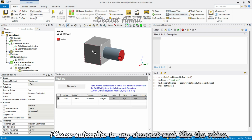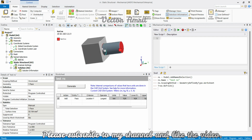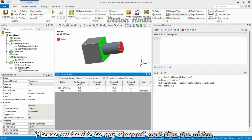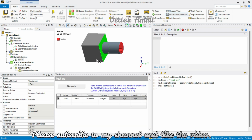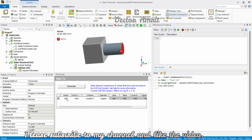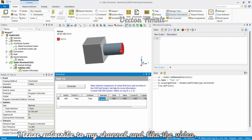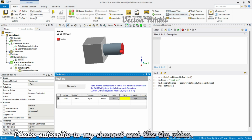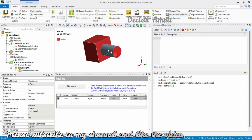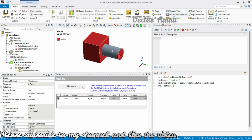Suppose I want to select all the flat faces, let me see what the y location is here. It is 13.38 mm, whose faces are greater than 13.38 mm. So what I will do here, instead of this, I will just type planar faces. If I generate, you will see all faces are selected, not cylindrical, because here I have not chosen cylindrical. From here I will filter out.